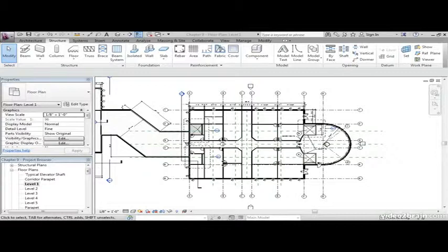The objective for this lesson is to start adding structural grids to our model. We'll add vertical alphabetic grids and horizontal numeric grid lines to the east wing. Then we'll add a radial grid with an offset of 6 inches and two 45-degree angle grids to complete the radial entry. Open the file you've been working on, or open the file called Chapter 9 and follow along.